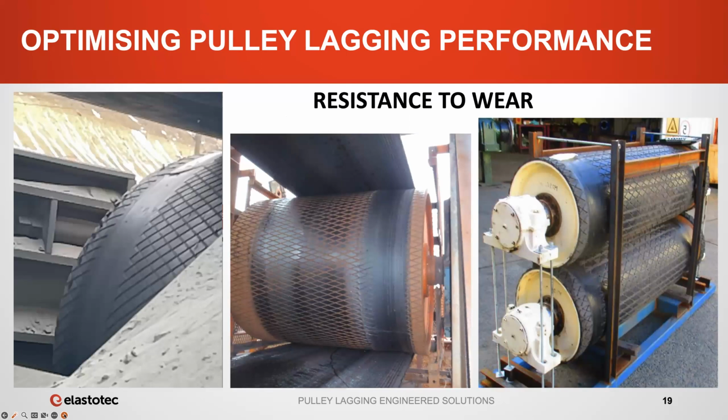And this is often due to localized shear forces on the pulleys due to factors such as short belt transitions, turnover conveyors, uneven belt stretch and recovery with things like PVC solid woven belt. The photos on the left-hand side and the center are on a conveyor with a turnover belt, and the photos on the right-hand side are from contact with a PVC solid woven belt.